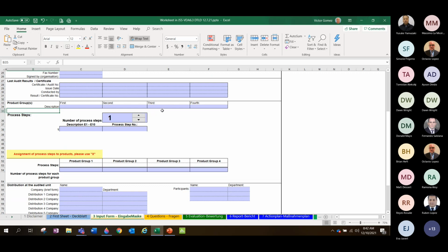First one, an airbag supplier. They probably have a laser cutting process. They have sewing process and assembly process. And that is the case if they don't manufacture the inflator under the same roof. And then if we go and audit that supplier, the scope of the VDA audit has to be either one of those 3, or you're going to spend the time to audit the 3 processes. We have a laser cutting process, which is one. Then all those panels that are being turned into panels now after being webbing, after being a textile roll, now they are panels that will be sewn into an airbag product. So the second process of that company is sewing process.